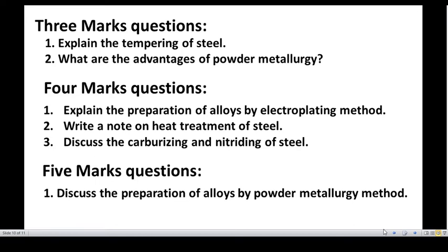In this method, simultaneous deposition of alloying compounds is done on the mold of desired shape, which is made the cathode, and a DC current is used as the current source, and the electrolytic solution of the metal salts which are to be alloyed is used in the cell. That means the metal to be deposited is taken in the form of an electrolyte, and in this method a good quality alloy is obtained.